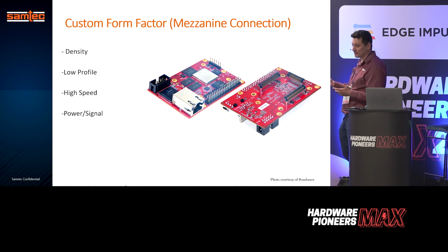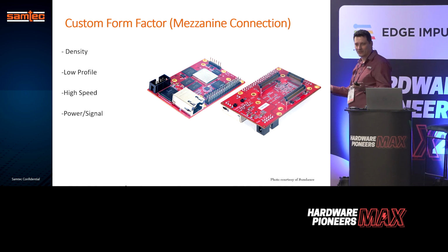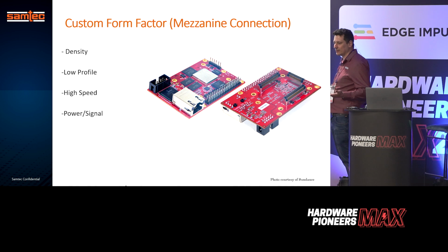So when we rate connectors, we normally look at the S parameters, return loss, insertion loss, and we assign a data rate. But obviously, it's not in the whole channel. So if you want to see how the connector is looking in the whole channel, is where we can discuss about it, where we can provide you the S parameters so you can simulate your whole channel and see the actual performance of your device, not just the connector itself.